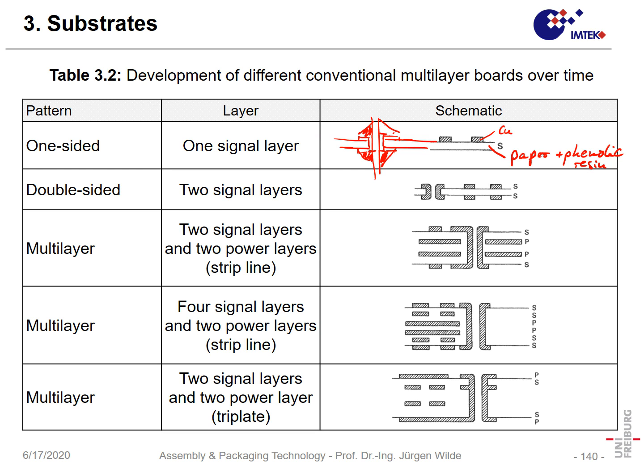The next thing was not only to have one layer with plated through hole, but to have multi-layers. For instance, in our case here we see 4 active layers, like 2 signal layers, 2 power layers, and we have a plated through hole through all of that board. This multi-layer was developed more and more. We had more and more layers.